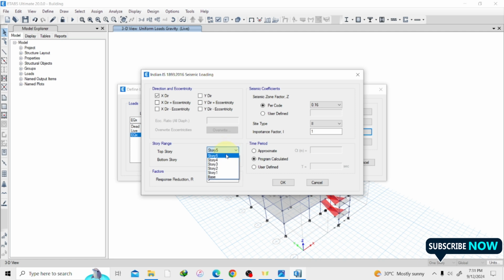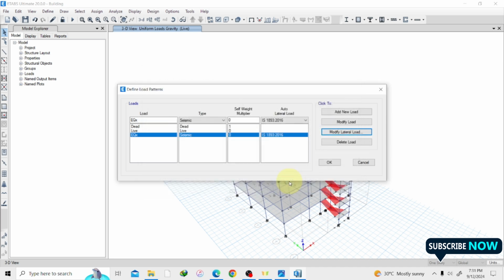With our top story, our last one is 5 and our bottom is the base. And with the time period, I'm going to let the program calculate it for me, so I'm going to leave it as program calculated. But if you want to input your own time period, you can also do that with the user defined. So now I'm done filling each and every section I'm supposed to fill for this seismic data. Once I'm done, I can just click on OK.